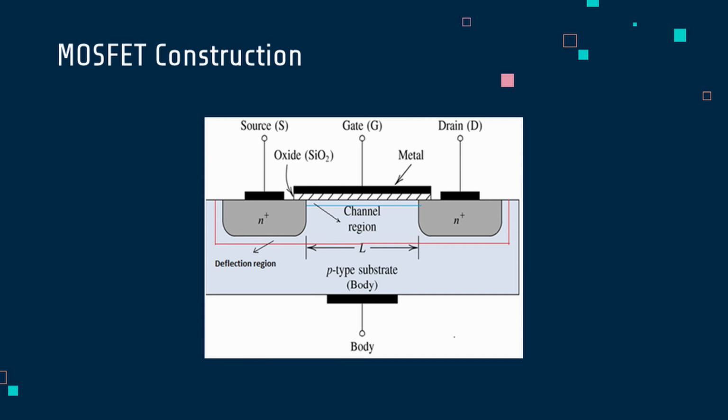Similar to diodes, MOSFET transistors also utilize doping, which is usually performed on silicon. Instead of a simple p-n junction, transistors contain multiple sections, such as an NPN or a PNP junction. The diagram shows the layout of a typical MOSFET. Two regions, the source and the drain, are doped with an N-type dopant, which each form their own depletion region along a border with a p-type body. This way, when no current is applied to the gate, the depletion regions prevent current flow across the transistor.